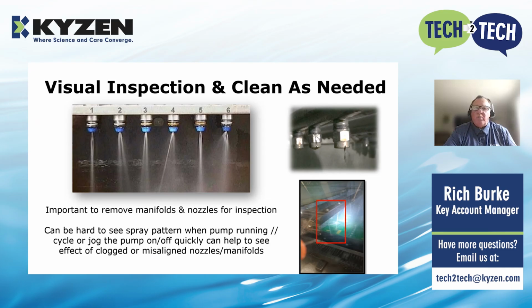So one thing that you can do in that case, if you're trying to do a visual inspection inside a machine, you could jog the machine on or off, or the pump on or off quickly, and look at it, and that can give you an indicator of a nozzle that's clogged or not. But in many cases, you want to remove the manifold itself, remove the nozzle, and actually clean the debris. And again, you're just seeing here some of these examples of nozzles that are being sprayed with varying degrees of debris or a clog. So that's very important.